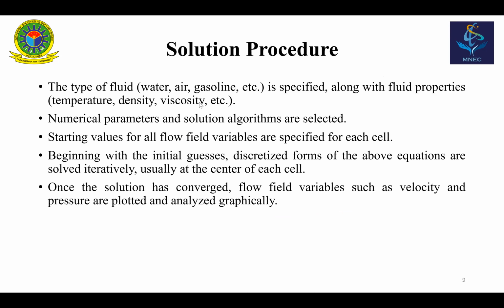And then we have to introduce our coolant, that can be water, molten salt, or water with boric acid. And then we have to create the numerical parameter and the solution algorithm, and do some initial guesses, and then run the simulation and see whether it converges or not.